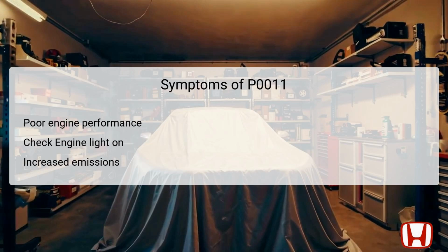The symptoms associated with DTC P0011 can vary in severity, but generally include poor engine performance, which can manifest as a loss of power, rough idling, or stalling. Typically, when this DTC is activated, the check engine light will also illuminate, indicating an issue that requires attention.